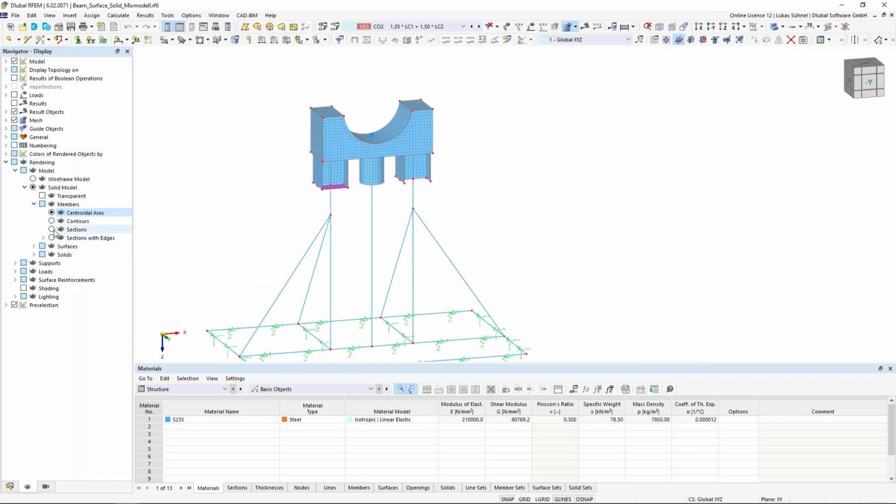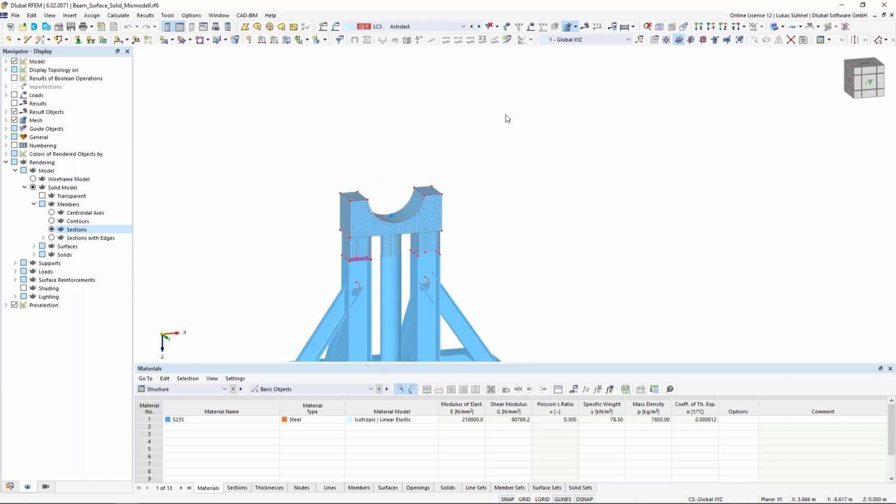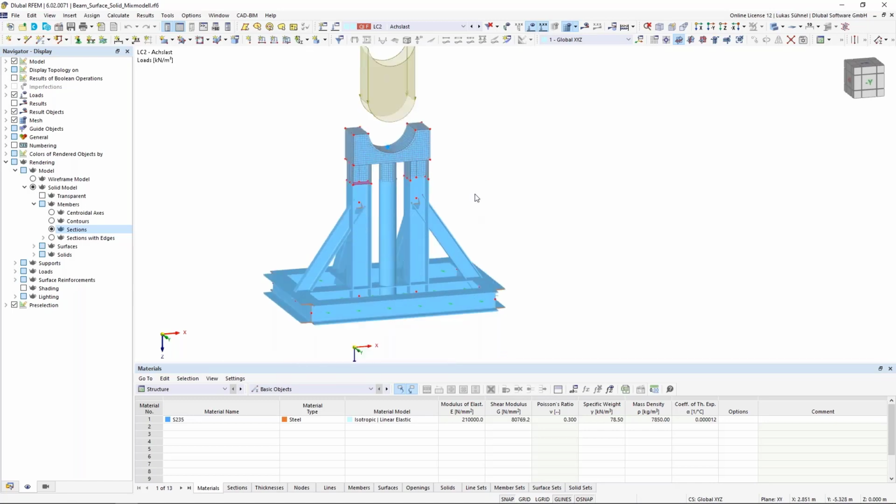So far regarding the modeling. Regarding the loading, these are German names, never mind. I have two load cases. I have my dead load case here, and then some load in my live load case. That's all I want here in that example. And of course, we have the combination of those load cases using an ultimate limit state design situation and a serviceability limit state design situation.